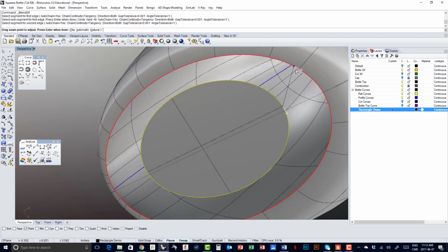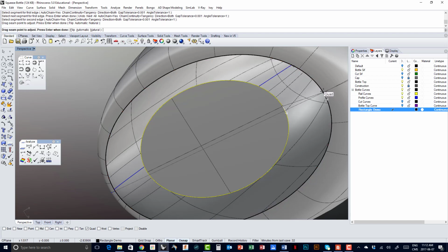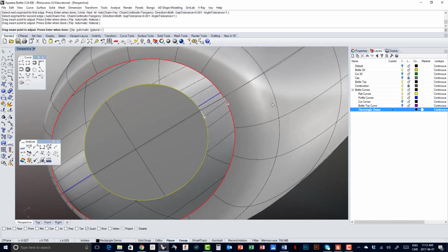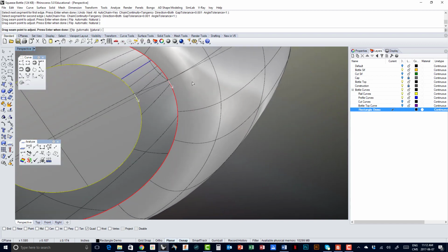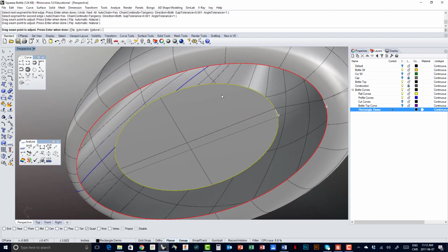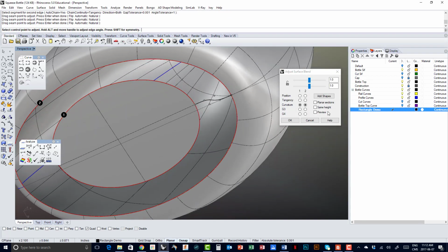They're not perfectly aligned, they're going in the same direction. So what I'm going to do is activate my quad snapping toolbar, left click on this arrow and just drag it until I grab the quad of my ellipse like that. So now I'm properly aligned, so I will avoid any twisting effect, and I just right click again. I can click on preview.